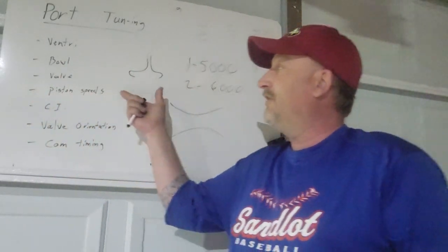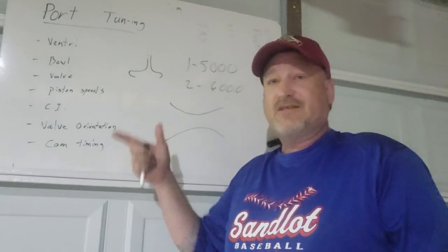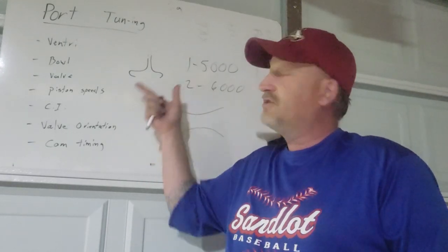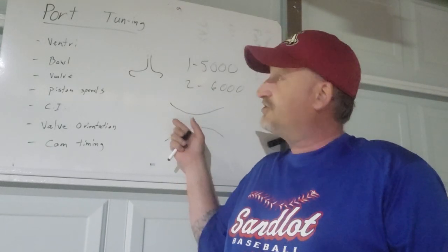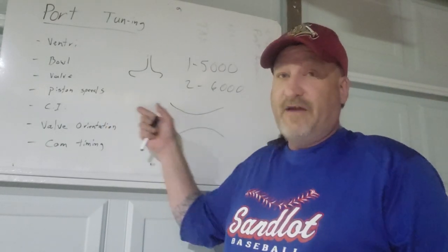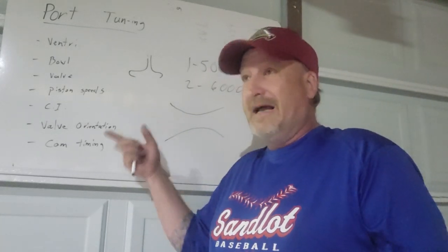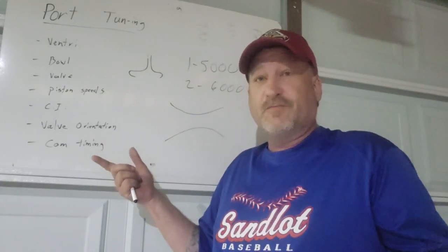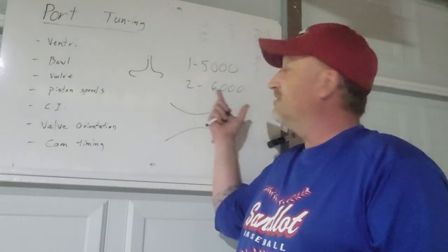Okay, all the things that we just talked about, piston speed and the rod ratios, that's also going to alter the port tuning within the RPM range. So the port has to match the piston speeds, the vacuum that's created, to allow it to get the most efficiency or the most power per cubic inch within the RPM range, wherever that may have been intended.